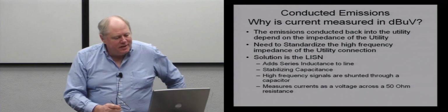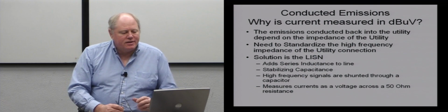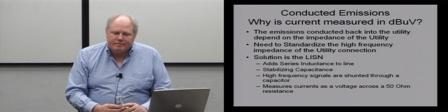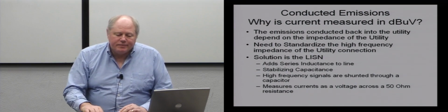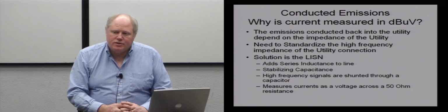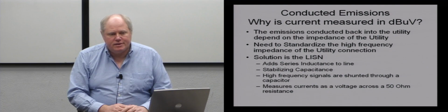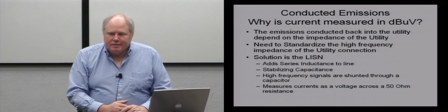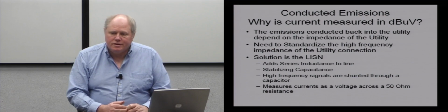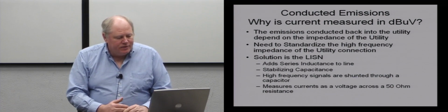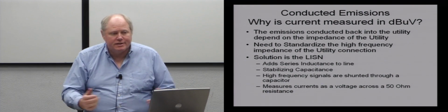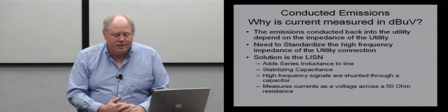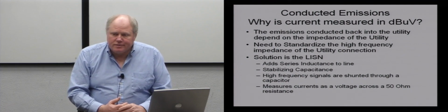The problem that you have when you're trying to look at how things, say, are conducted into the utility is any circuit, if you have a source that's going to drive, the impedance that you connect to that source is going to determine how much current flows. Well, what's the impedance of the utility system? How do you determine that? You can't really hook an ohm meter up to the wall. And if you did, you probably would find different results at different places. Might depend where you are in a building like this. Might depend where you are in Minnesota or what country you're in.